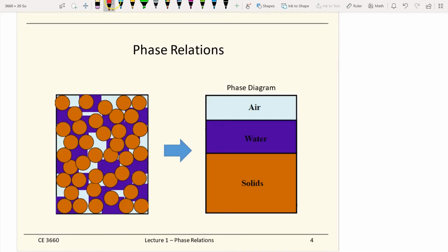So we have learned the soil matrix is made up of air, water, and solid. The void is the part occupied by air and water, and the void is between all the soil particles. Looking at this picture, all the space in between those soil particles is void, and the void can be occupied either by air or by water.